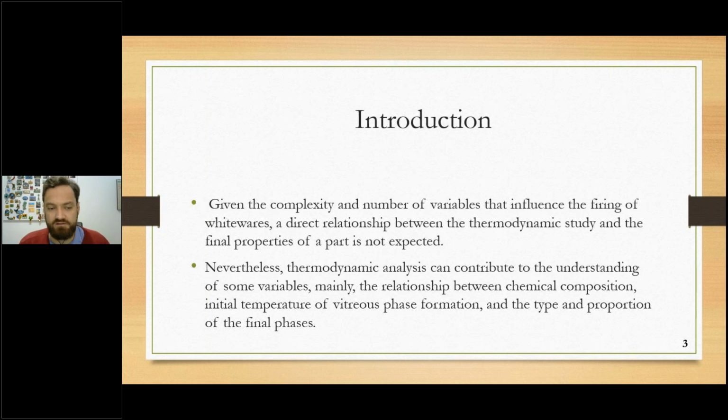Given the complexity and number of variables that influence the firing of whiteware, a direct relationship between the thermodynamic study and the final properties of a part is not expected. Nevertheless, thermodynamic analysis can contribute to the understanding of some variables, mainly the relationship between chemical composition, initial temperature of vitreous phase formation, and the type and proportion of the final phases.